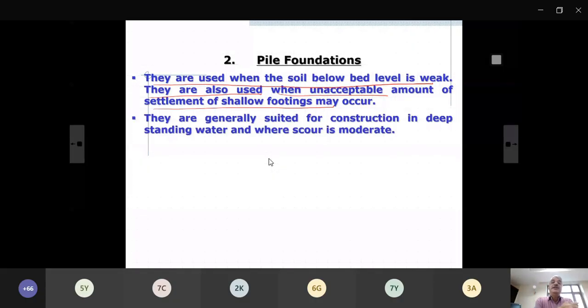And these pile foundations, nowadays you will find at 99 or 99.5% bridges, wherever you might have gone in the field, except very, very rare, very wide rivers carrying heavy flow, normally people go for pile foundation. The biggest advantage of pile foundation is their construction is very, very fast. Construction is very fast as compared to well. Well takes 2-3 years to sink.